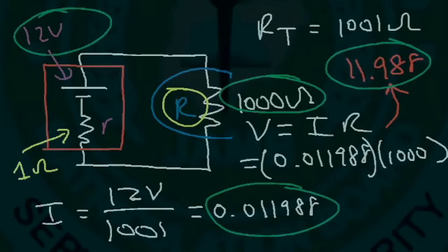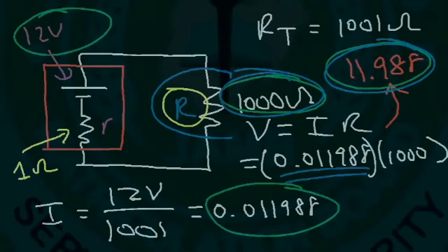So notice that whenever the internal resistance of the meter is very high, the reading is more accurate. So that's why voltmeters have a very high internal resistance, so they can measure voltage properly. And the second reason is that by increasing the internal resistance of the multimeter or the voltmeter, it draws less current, which puts a smaller load on the battery, so the voltage doesn't drop as much. Whenever the current in the circuit is high, the voltage drop is high, and so it's going to be difficult to measure the actual voltage of the battery.